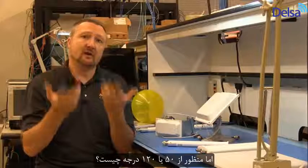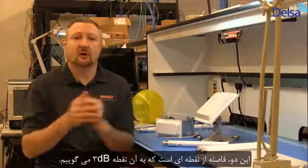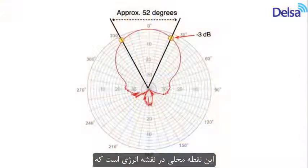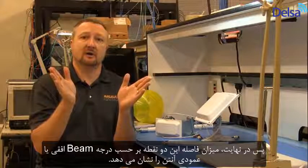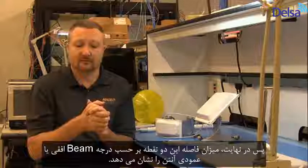And when we say 50 degrees or 120 degrees, what does that really mean? Well, that's referring to the distance between what we call the 3 dB points. The 3 dB point is the point on the energy plot where the power has been reduced by 50%, or 3 dB, from the peak power in the direction of maximum gain. And the difference between those 2 points in degrees is the horizontal or vertical beam width of the antenna.